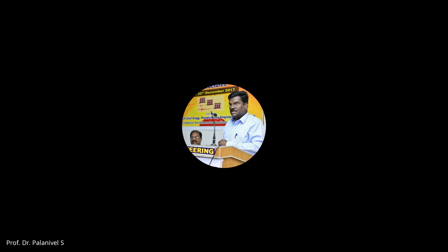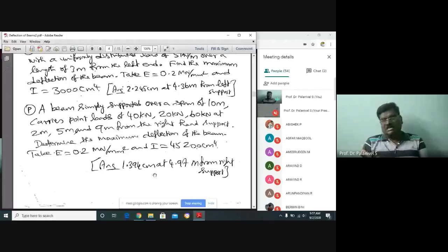Now only point loads. Consider the last portion. Now the beam is divided into four portions because there are 3 point loads acting on it. Take A as origin. Take the last portion and consider the section XX in the last portion at a distance x from A. Now you write down the general expression for bending moment for the last portion. The general expression is divided into four parts.